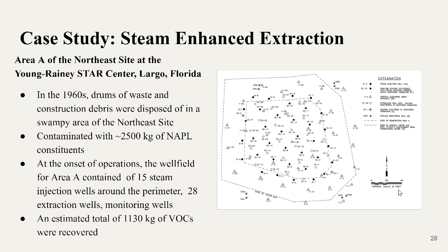Electrodes were placed in both injection wells and extraction wells. This design was chosen in order to optimize the heating and minimize drilling and construction costs. Steam was generated from softened water using a diesel-fired boiler system with 4 units. Steam was piped to the injection wells using steel pipe, and the pressure was regulated at each wellhead. Steam flow rates were measured for each injection interval using orifice plates with differential pressure gauges.